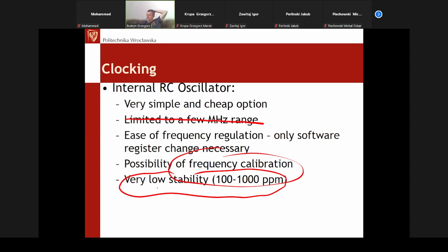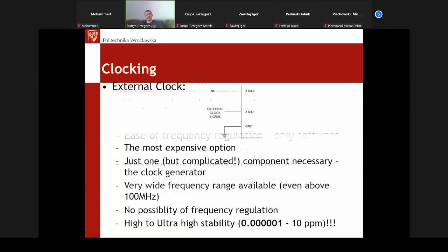So for a USB interface or UART interface, if you intend to use them, don't go this way. Don't try even with internal RC oscillators. Again, I saw synchronization circuitry for the clocking of the USB itself, to make USB run from internal RC oscillators. So it is possible. People like internal RC oscillators because they are cheap and no additional component count is necessary. Therefore, I would suspect more developments in this range in the future in case of internal RC oscillators.